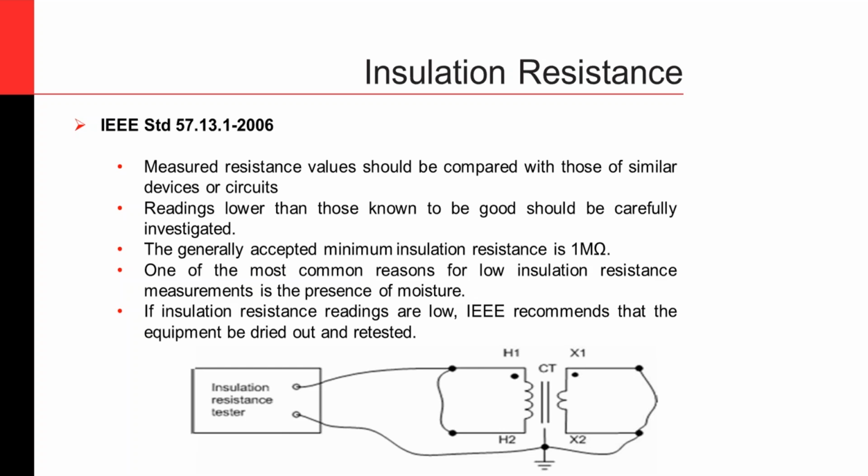On what basis do you decide whether the CT is going to go bad and you have to replace it? If I'm the testing engineer and have to make decisions based on that, I'm going to do a winding resistance and insulation resistance test. That gives me a very good idea of how the insulation on the CT is, and is it deteriorating, or is it something internally wrong with the CT?